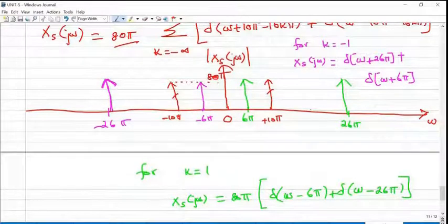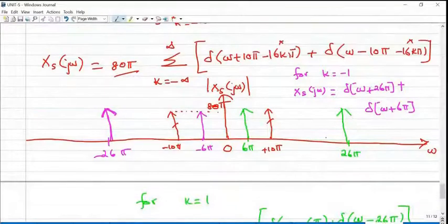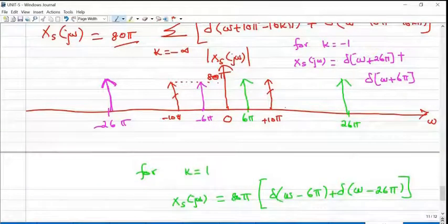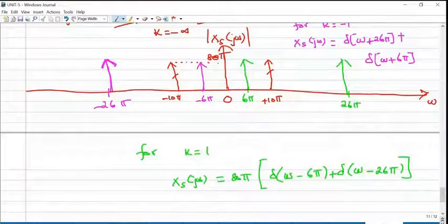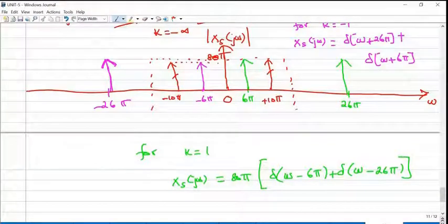As per the Nyquist sample rate, we already stated it is not possible. So once again, we are going to prove it in terms of magnitude spectrum. See here, we need this component. If we design a filter like this, can we get our information alone? No. There is another set of spectrum components available here. So the spectrums are overlapped with the neighbor spectrum. Each and every frequency spectrum overlaps with the other spectrum, so it is not possible to recover our actual information.